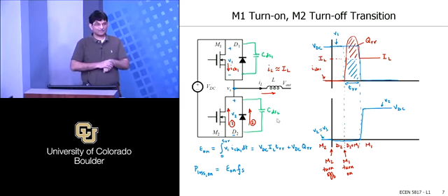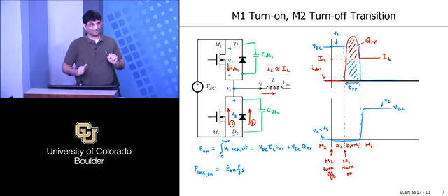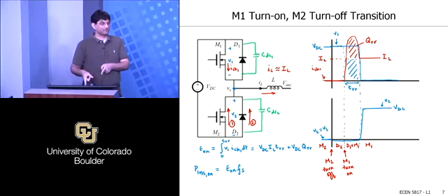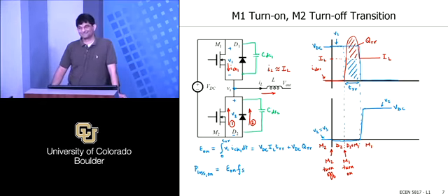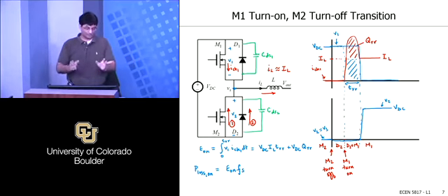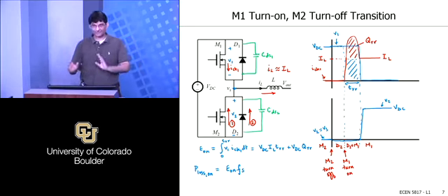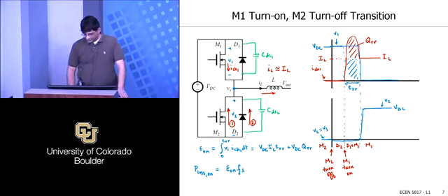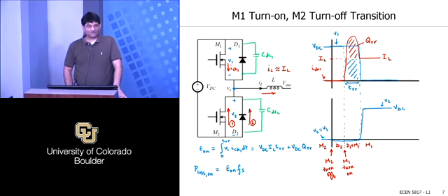So when I said you have a slow device, you can add more capacitance, well, that doesn't come for free. It helped you in that transition, but it hurts you now in this transition. So nothing is free in this world. That's the kind of thinking you will become really good at as this course progresses, because you'll look at this and say, okay, should I add capacitance here? Maybe I should, maybe I shouldn't. This is what's going to happen. This is the kind of stuff that will take us beyond intro to power electronics, because you're going to be able to figure these things out quickly.